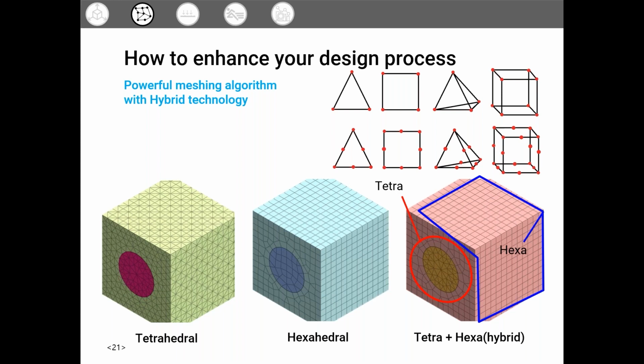However, in other programs, you can't control the mesh size and mesh shape at all. You may click just dense or coarse for your density. The square boxes: the first one is made of all tetrahedral elements. But in this case, your modeling can be heavy because of the number of elements. The second one is all hexahedral. In this case, you may see not a proper shape for your model, like a cylinder-shaped tunnel.